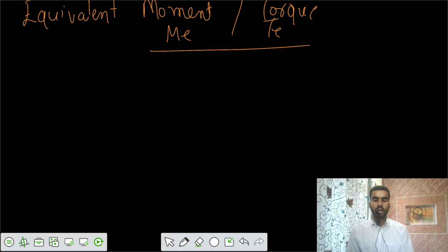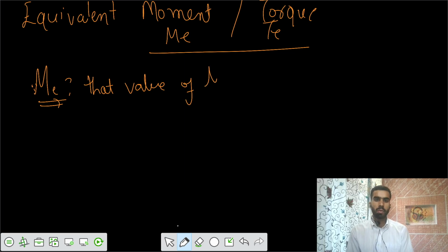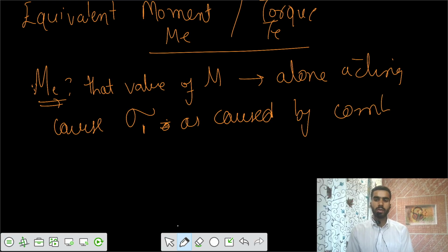If you're talking about ME, it's the value of bending moment which, if acting alone, would cause the same major principal stress sigma 1 as caused by the combined effect of torsion and moment.